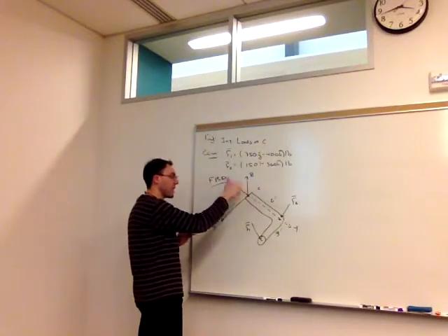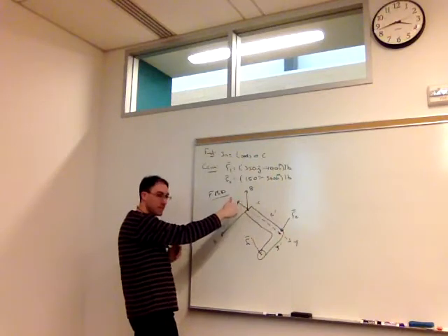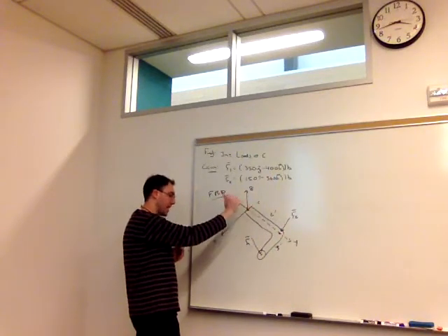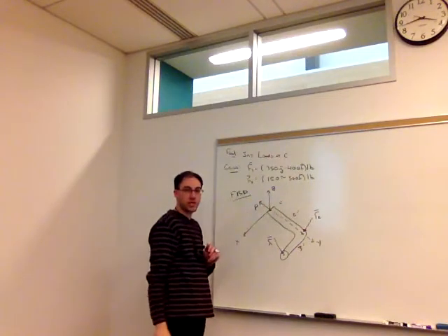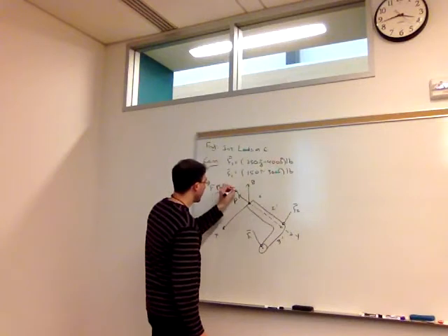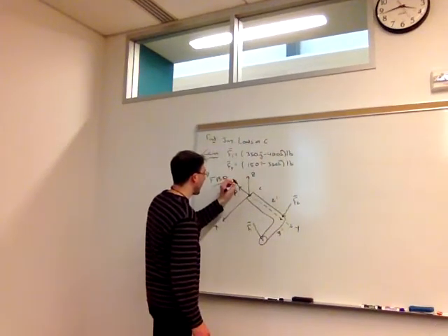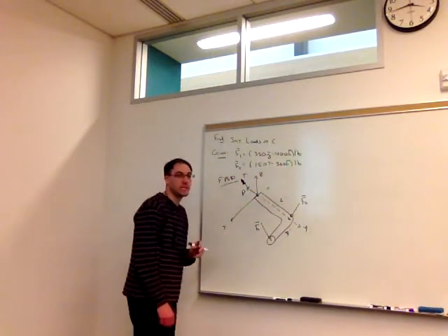Now that I know the direction of my internal normal force, I can draw the torsional moment. If I put my right thumb in the direction of P, the way my fingers go is going to be the direction I assume for T. Or I can more easily represent it as the double head arrow like we saw in chapter 4 and call that T. Either representation is fine.